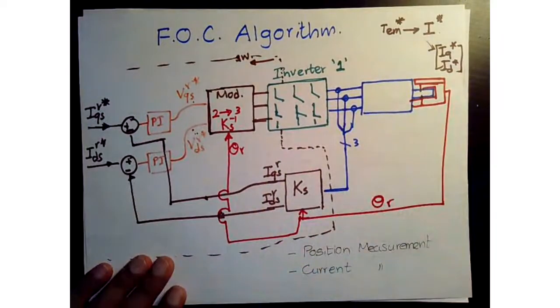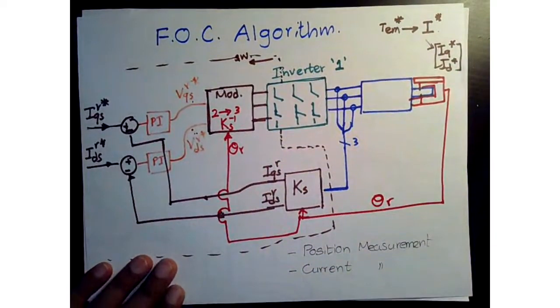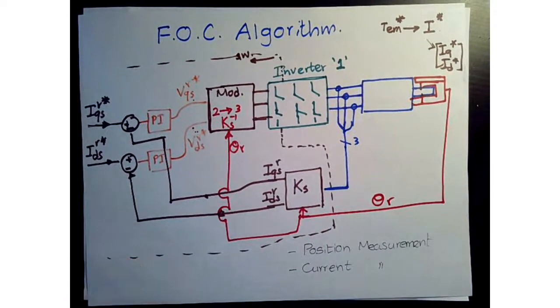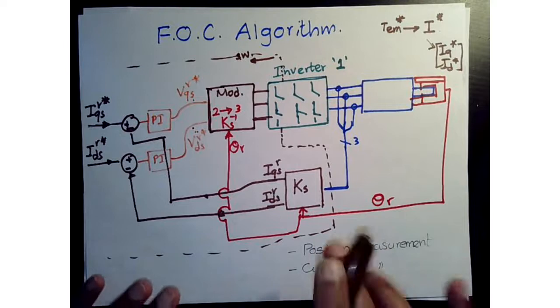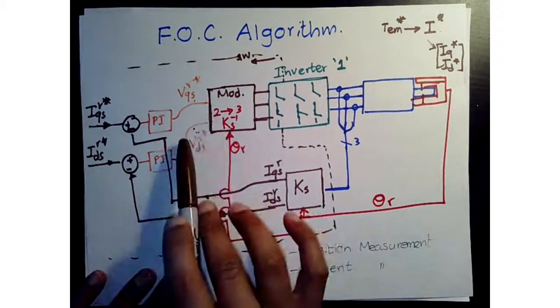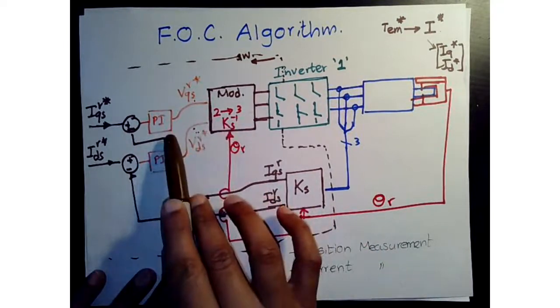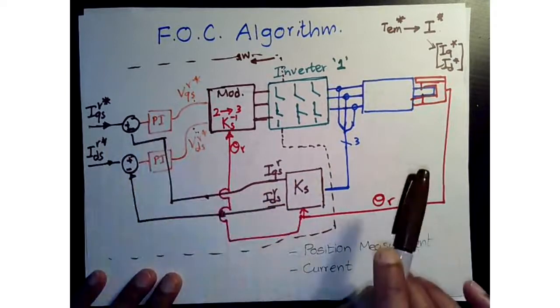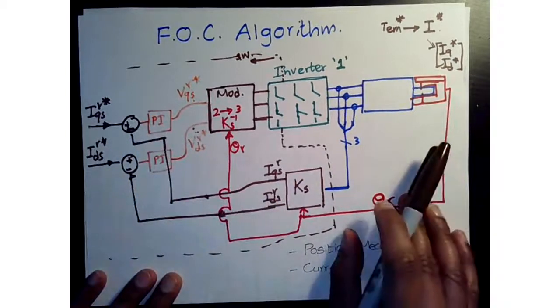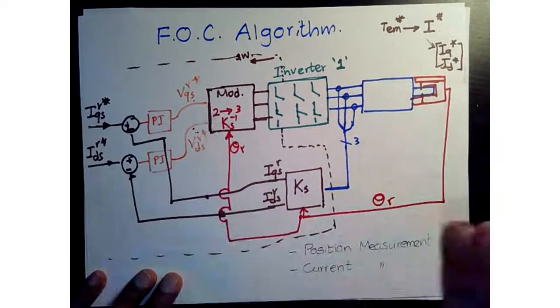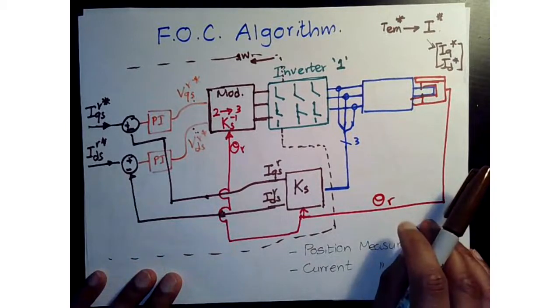If you go back and look at our DC motor controls, if you have one pole, you can control that with a PI controller without going into a great deal of control theory. You can control, stabilize, and achieve very nice performance with a PI controller by canceling the pole with a zero. Very simple method to design a controller. And then you can set your bandwidth based on what you want to achieve.